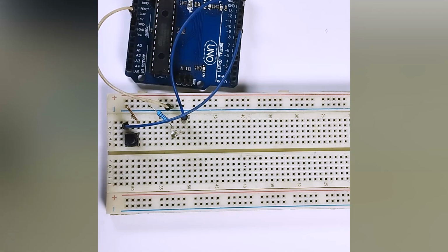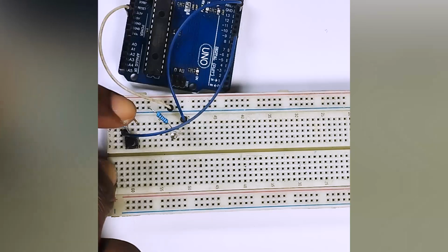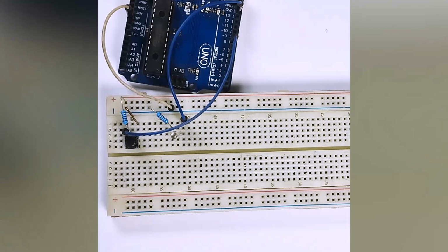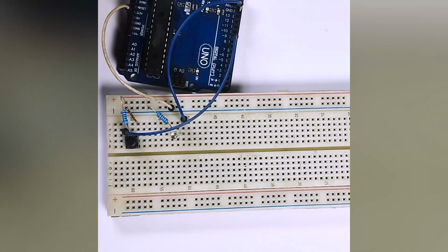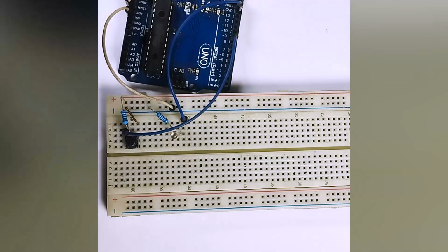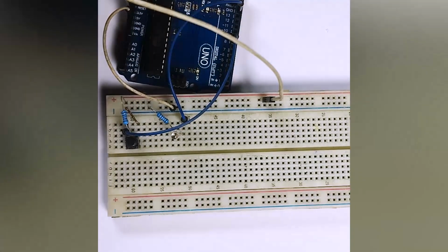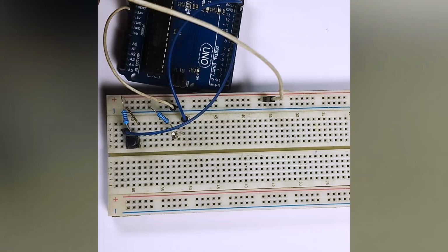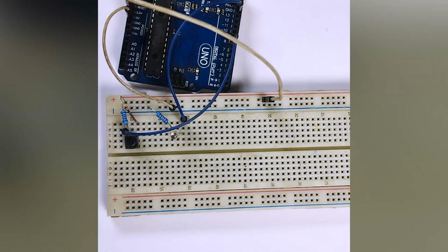Okay, so we have our pin 8 connected to this pin. We can then connect this pin via a resistor to 5 volts. Then we can connect that positive rail to 5 volts on the breadboard. We have 5 volts just after ground there. Since we've connected our 5 volts to our positive rail, we are done with this.